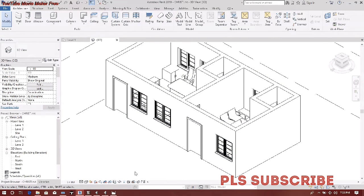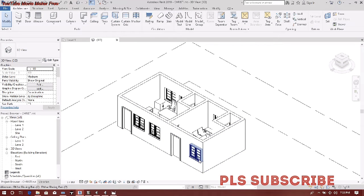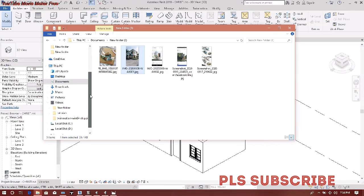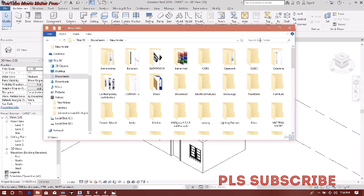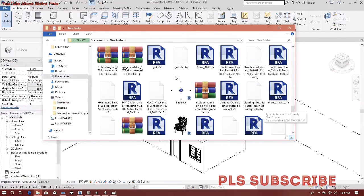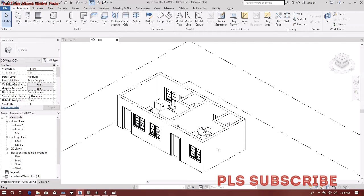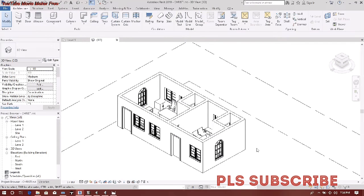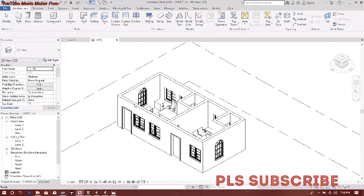So I think I've covered how to drop windows. Just a brush on that: we'll go to where our template is, which mine is here. I type whatever I'm looking for, which is window, and I have my windows here. When I see the window I desire, just drag and drop. Then it applies. You can apply on 3D and you can apply on 2D. That's just that, but that's not why we are here.